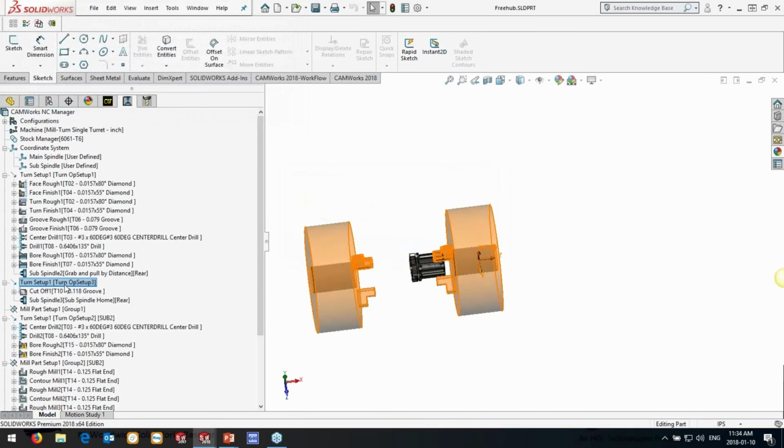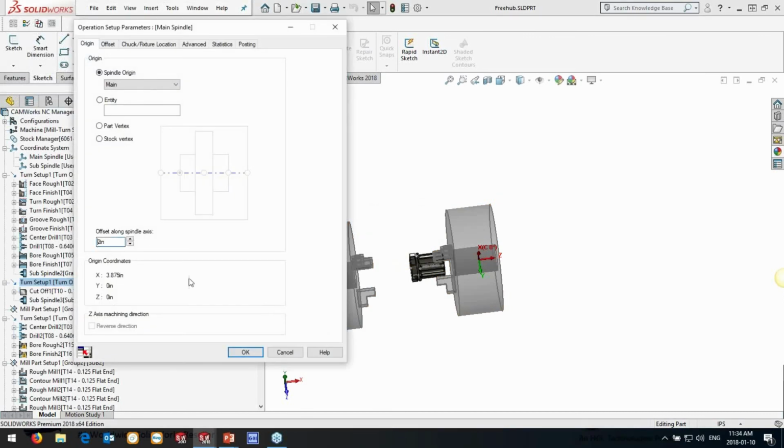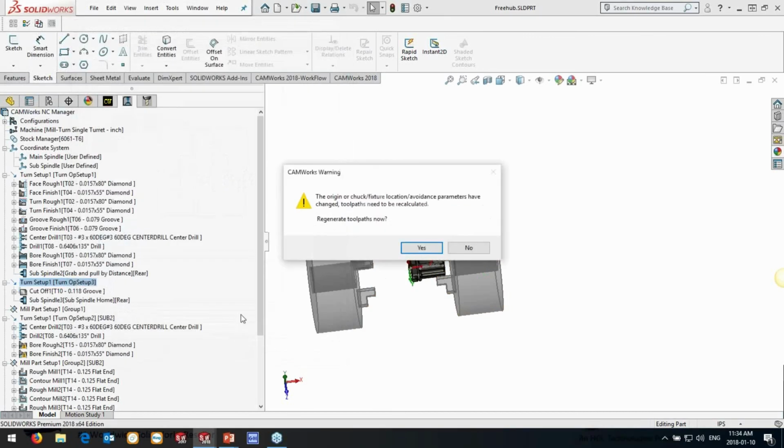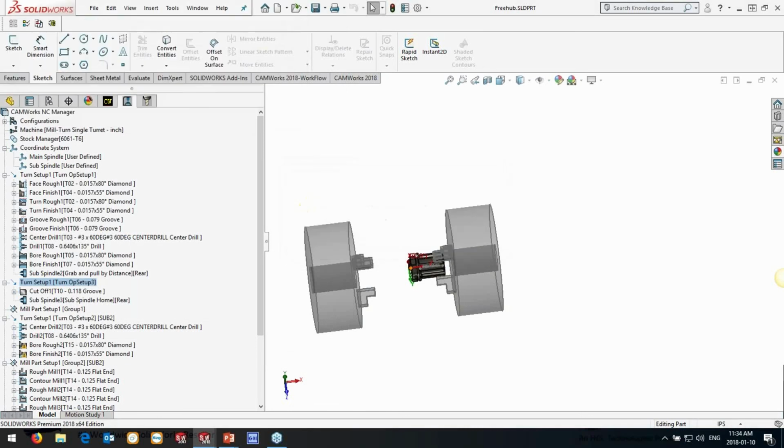So in reality, sorry, that was -2 inches here, because this is basically the physical home position on my machine, but I actually just pulled it out by those 2 inches, so it's actually shifted position. So the cutoff is now going to occur at this position, and then it takes it home. So the sub-spindle transfers can be customized to exactly what you want to do.